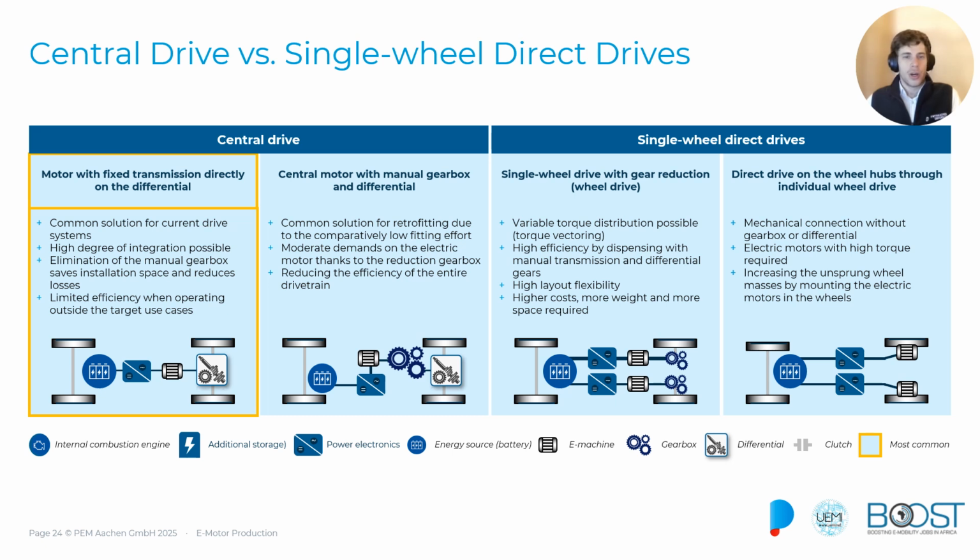We see newer cars coming with a maximum of 2 gears to help the electric motor to always work in the most efficient operating point. If you remember back to the motor map diagram on the slide where we compared the radial flux motor and the axial flux motor with each other.